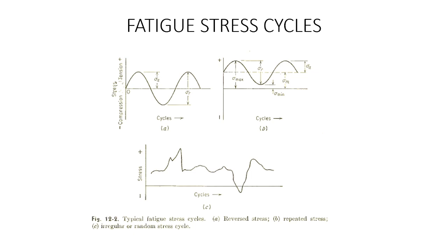Now you can see the second diagram. Figure A represents the normal stress strain cycle, which we can see in a normal shaft. In the second diagram the sigma m is shifted towards the tensile side, so there are no compressive stresses, only tensile, the positive mode.